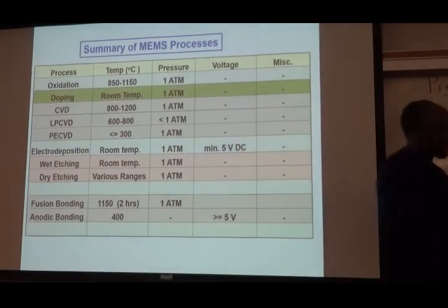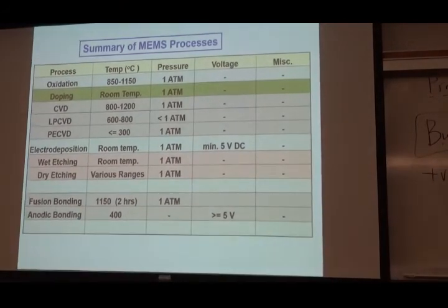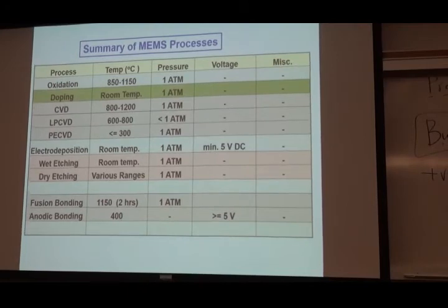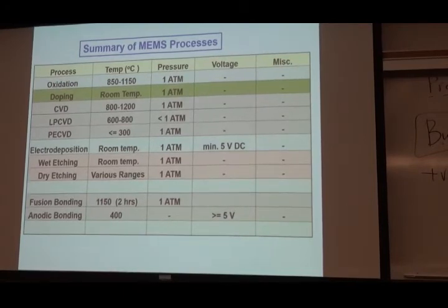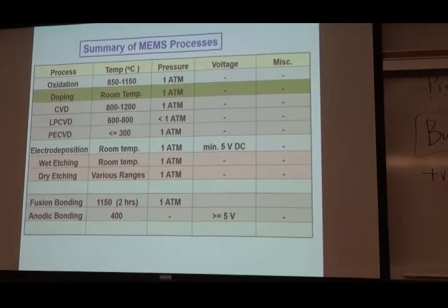Pressure, extremely low. To reach 10 to the power minus 9 torr, you need 2 types of pumps. You need a roughing pump first, just to bring it down to 10 to the power minus 3 torr. Then after that, you need molecular pumps. Okay? So that brings you to 10 to the power minus 9, but it's not going to happen in 1 hour.